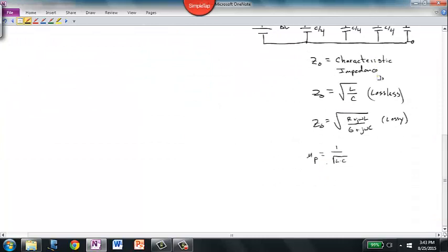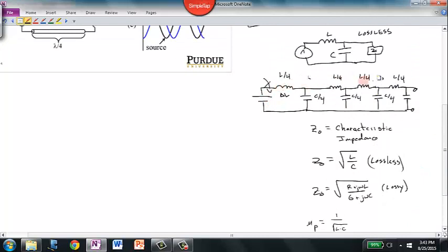Later in the course, I'm going to more rigorously develop the formula for characteristic impedance of both the lossy and the lossless transmission line. For now, the important thing to remember is that the characteristic impedance Z0 of a transmission line is the impedance of the line as experienced by the battery or other source while the signal is moving down the transmission line. So characteristic impedance is what does this battery know about the signal before the line has become fully charged.